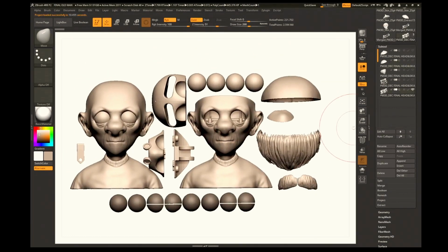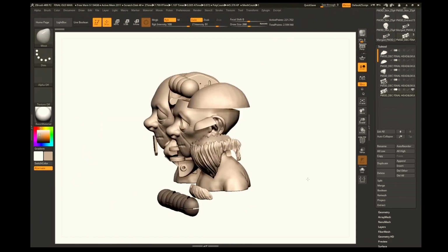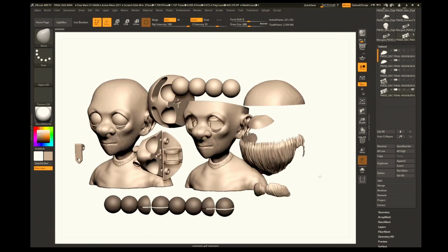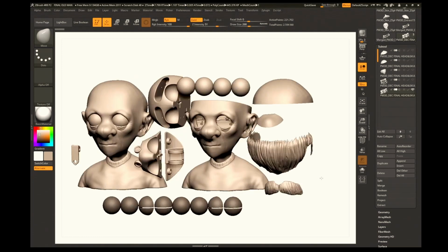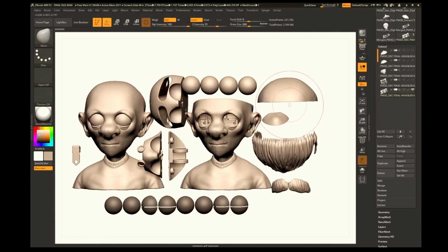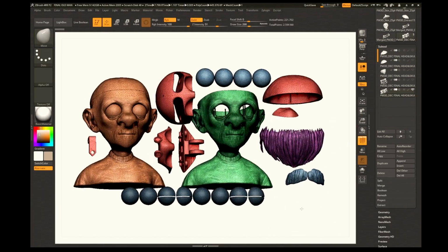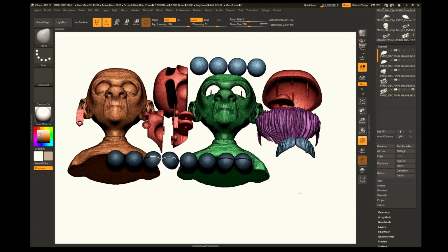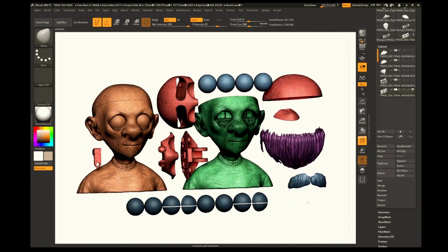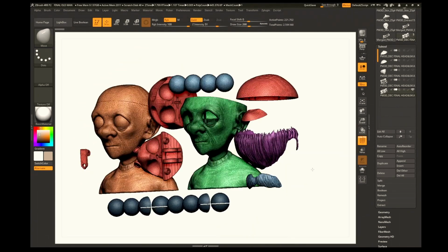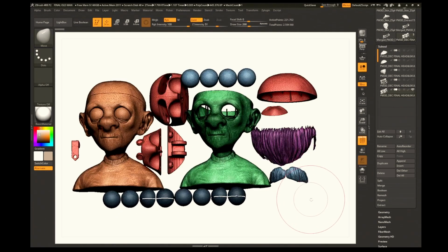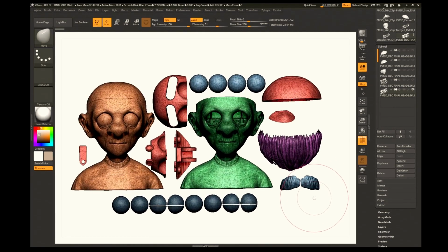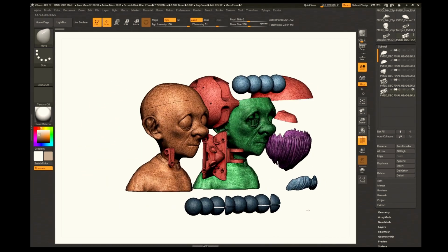Okay, here we have the model and the skeleton and all the components in place for going to the 3D printer. And that is decimated geometry. So I'll just turn it on so you can have a look at it. When you decimate, you're reducing the amount of geometry, so it makes the OBJ a little bit lighter for processing. I don't have the most powerful computer in the world, so I'll take this into the slicer software, and it will generate all the scaffold and stuff for holding on to the bed of my 3D printer.